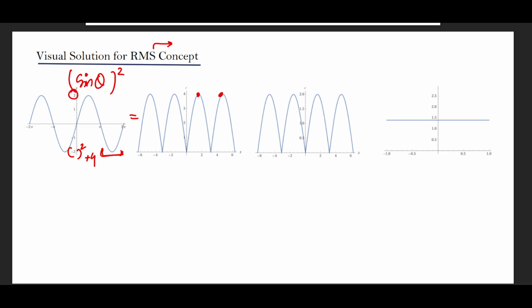Then, to normalize it back again, because I took the square, I'm going to take the under root of this whole function. This covers the root part of this RMS word. I've taken the under root again so that I can compensate for the square that I took at the very beginning. Now the values have come back to the original value, because the peak became 4, and now I take the under root, it becomes 2. Now the negative peak has effectively become positive.